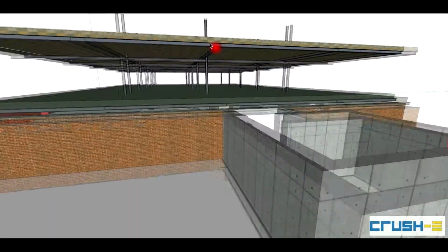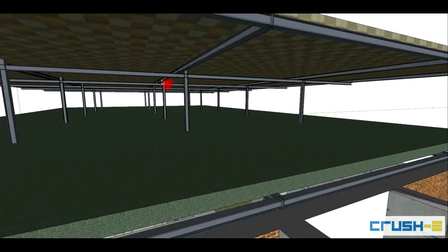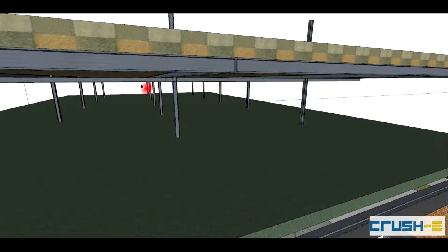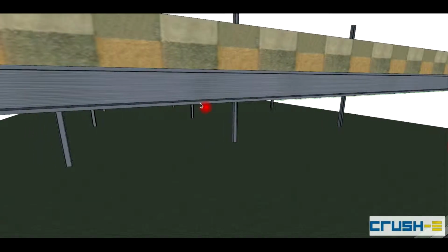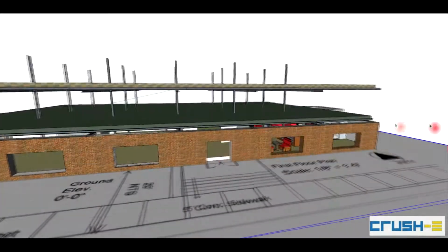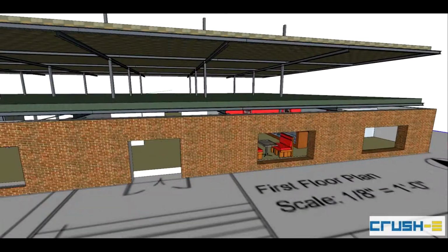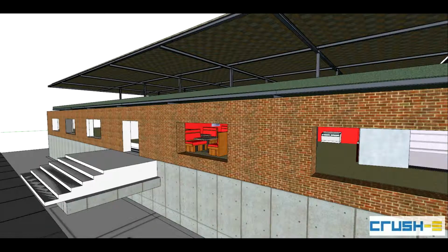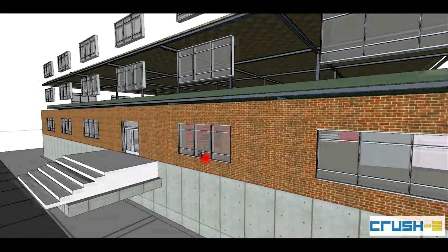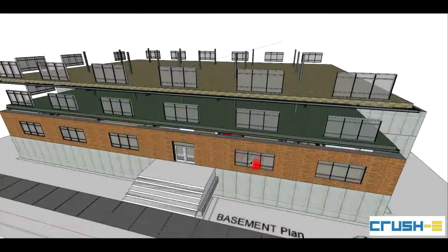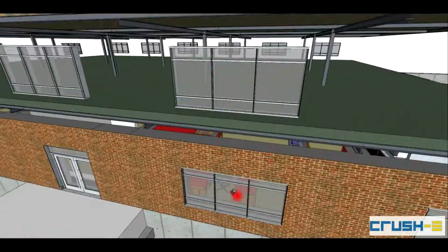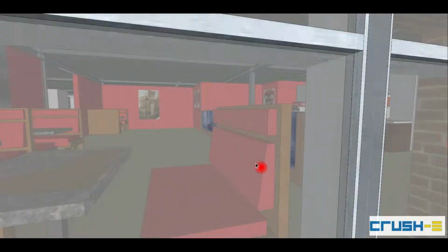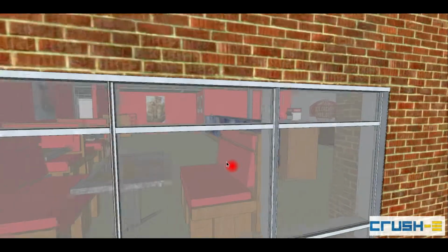It shows pretty much the grid outline of everything. So those are all the columns. There's girts underneath. I can actually put in bridge joists, or bar joists, or whatever needs to happen underneath, purlins, whatever. Get very detailed, but it makes a huge model. So try not to do that if we don't have to. But you can see with the windows in, that's the location of all the windows. I didn't do them by floor, but you can see the ice cream parlor. It's actually pretty awesome how that works.